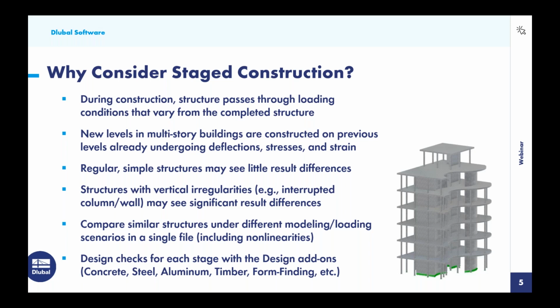The construction stage analysis add-on within RFEM allows us to compare similar structures under different modeling or loading scenarios in a single file. And we also can include nonlinearities with these comparisons. So rather than creating multiple files with the first level completed, then the first level and the second level completed, we can consider all of that in a single model.